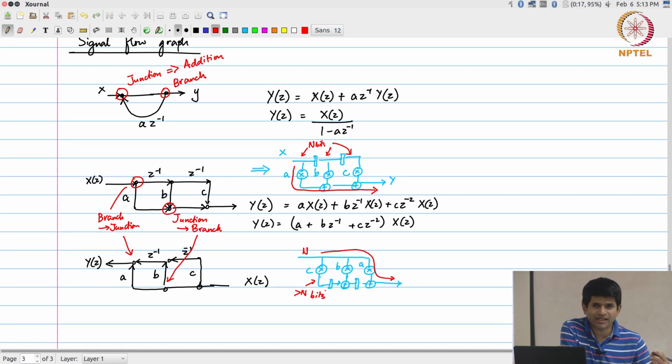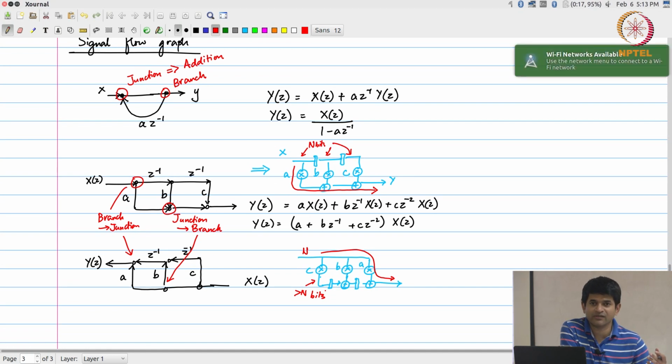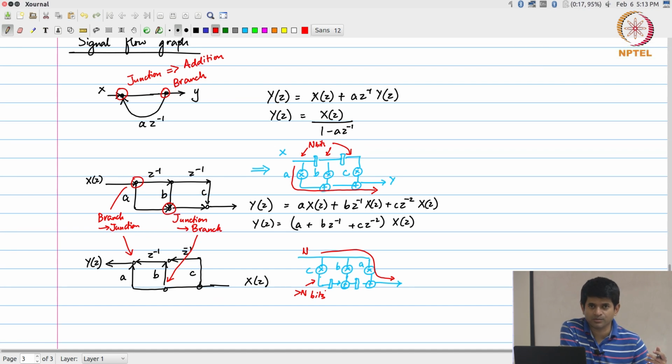I may be able to get around that by using a fixed point representation, and after the fixed point I know that it's fixed point anyway, so what I'm going to do at the end of the day is multiply, let's say, two 8.8 numbers, and I will round the result off also to an 8.8 value. If I do something of that sort, I may be able to get around this shifting problem. But nevertheless it is there, it is something that I'll have to deal with.